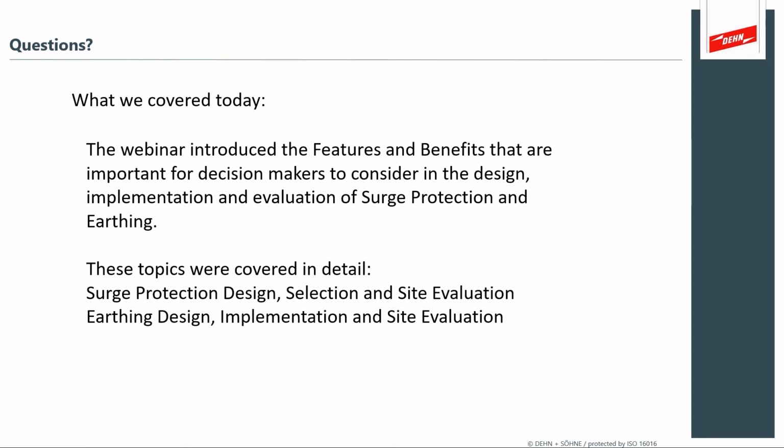Excellent. Those two factors are exactly what is considered. And remember, the IEC has the conservative assumption that 50% of the lightning current is being distributed into the soil and 50% is being diverted back into the electrical installation. So in other words, if you design a system for LPL3, which is a 100 kA lightning strike, the IEC assumes that 50 kA gets distributed into the soil, while 50 kA might be seen by the surge protection devices. So you need to make sure for this LPL3 design that you have a surge protection device that can handle a maximum of 50 kA lightning current.